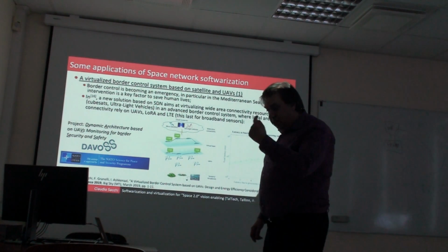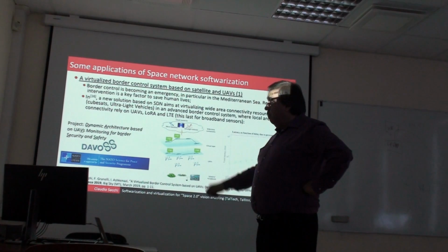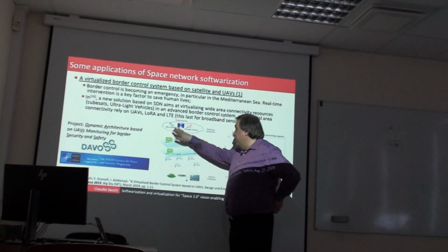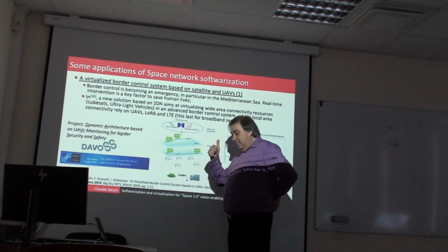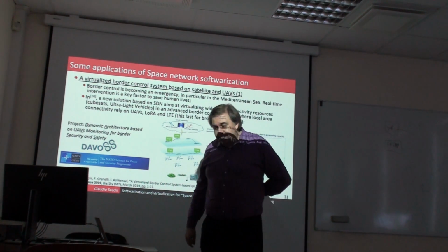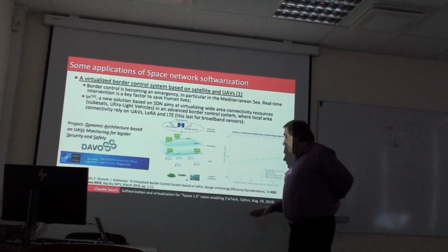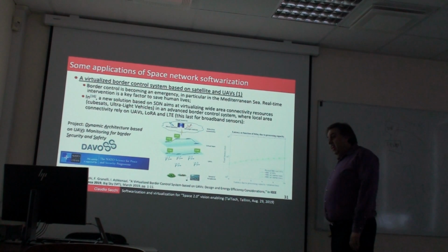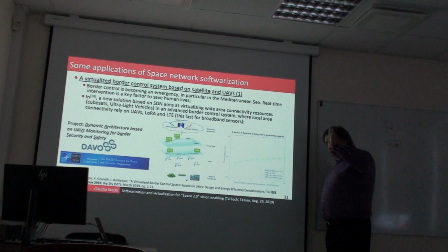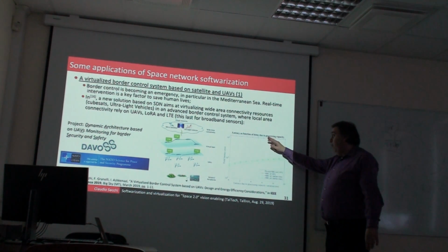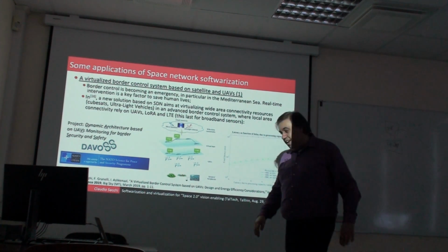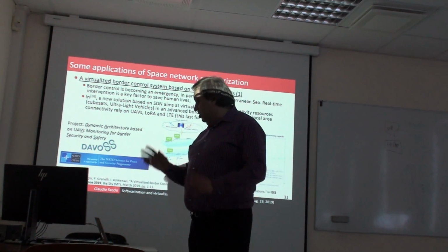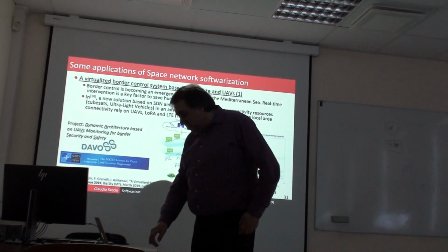Remember that in the old picture that I've shown at the beginning of the presentation, the splitting of functionalities from the radio head end to the baseband unit has throughput and latency constraints. We measured the latency. The latency of the CubeSat is of the order of 2, 3, maximum 4 milliseconds. At least tolerable. The latency of a geostationary satellite is of the order of half a second. That is not possible. So a geostationary satellite is better to host complicated processing architectures, but the latency avoids this.